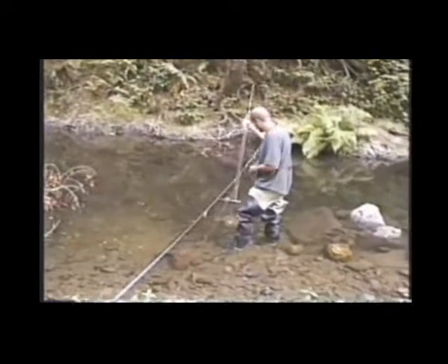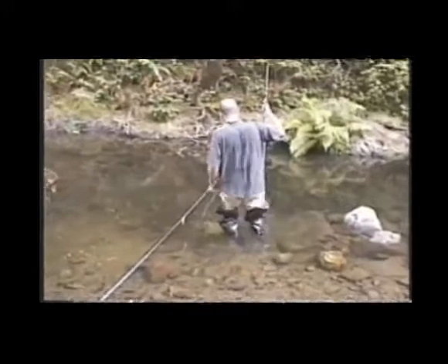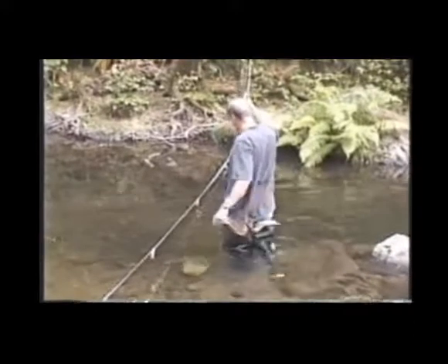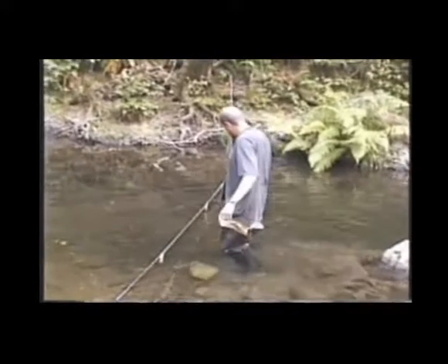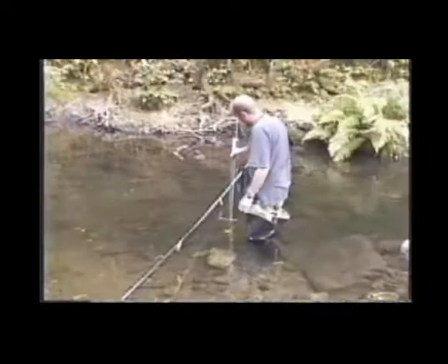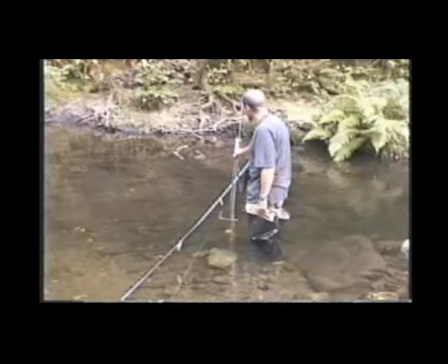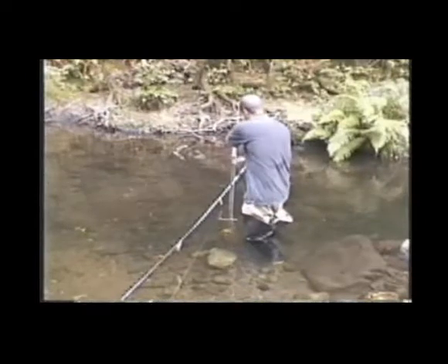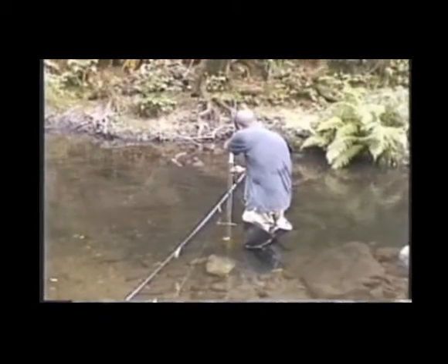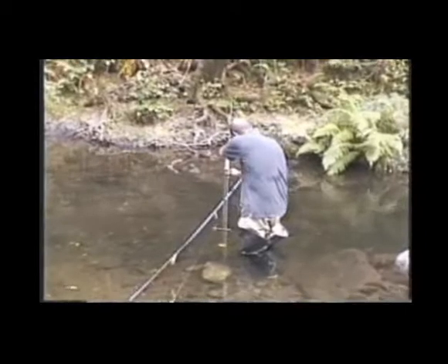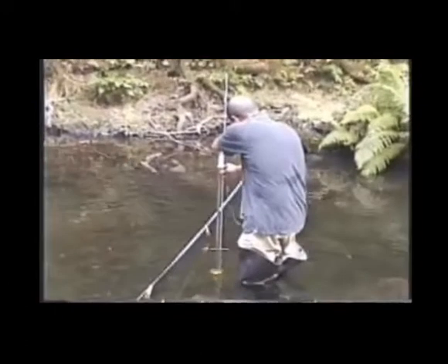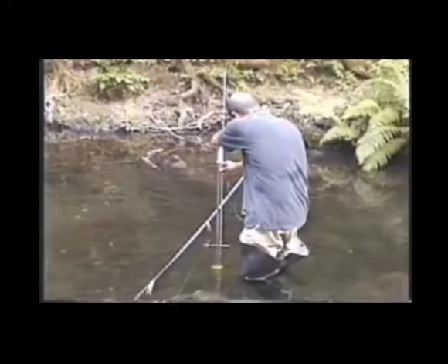And now the device is moved to the next site, and again placed securely on the bottom underneath the marker. Held vertically. It's very important to hold it vertically, and the measurement head is perpendicular to the flow of the current. Then the total depth is measured, and then using the vernier scale on the handle, the measurement wheel is raised to 60% of the depth, and the process is repeated again. Each time the process is identical at each one of the marked intervals along the tape.